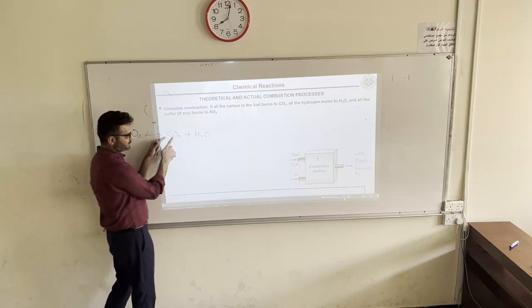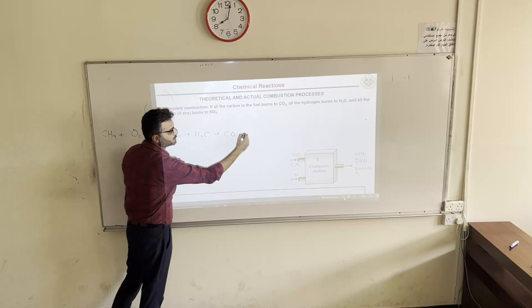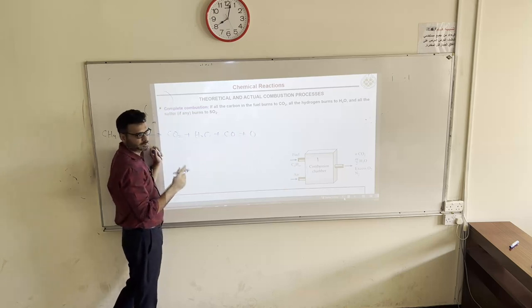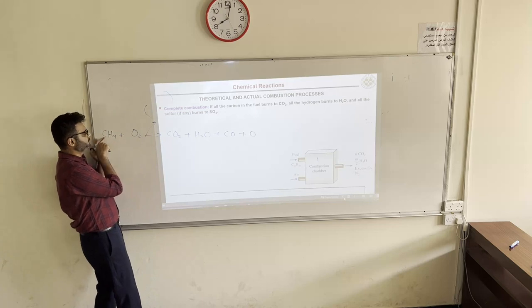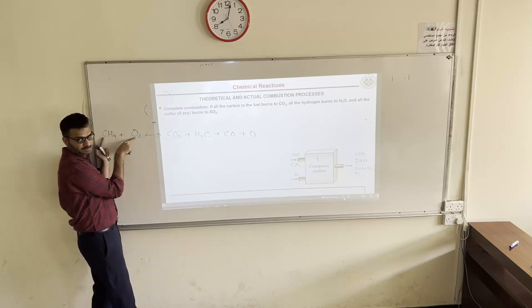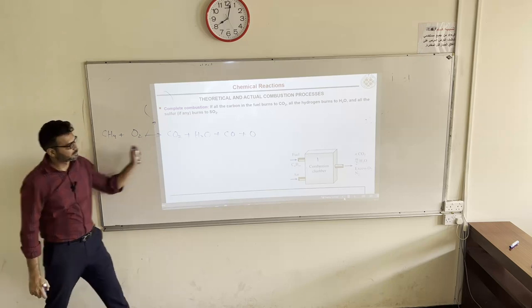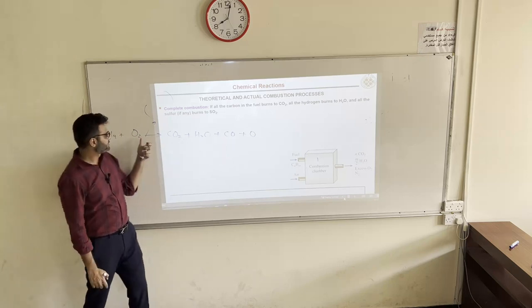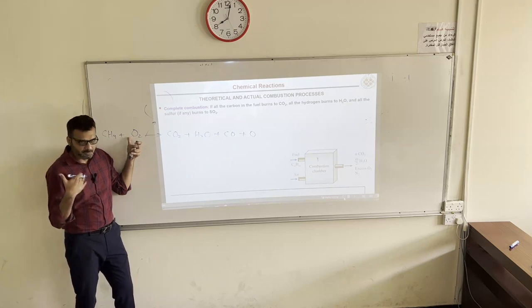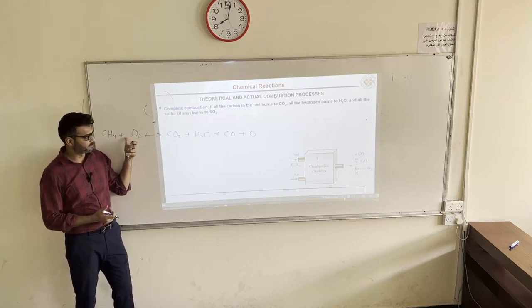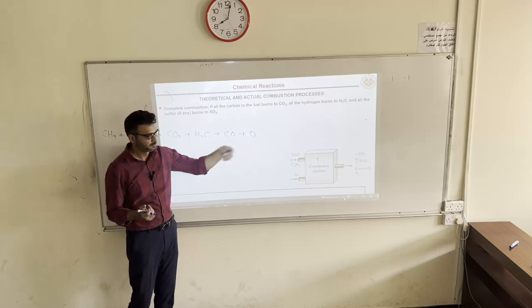If it does not react completely, then you will have CO or OH. The reaction was not complete, so some of the carbon does not react fully to give you maximum heat, and that converts to CO. Or you supplied too much oxygen, so some of the oxygen appears as unburned.